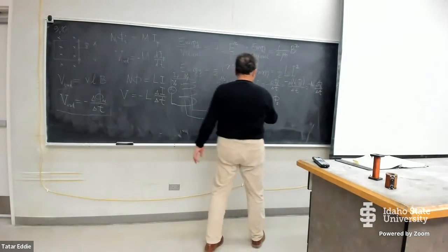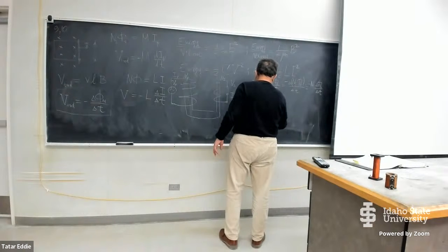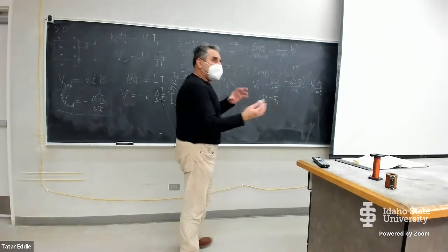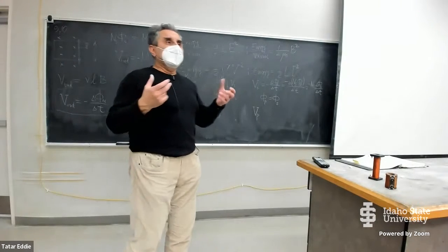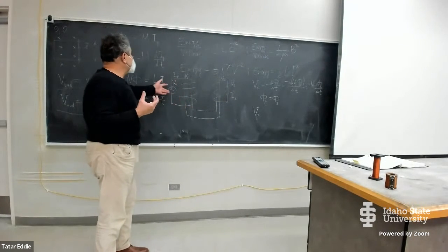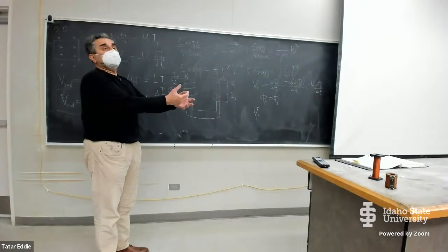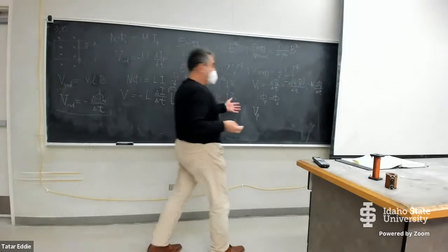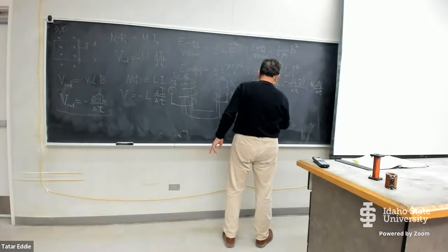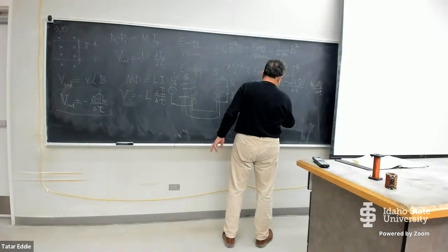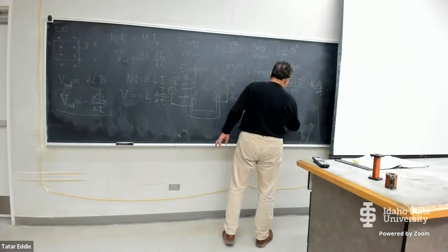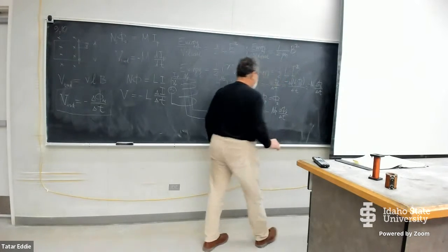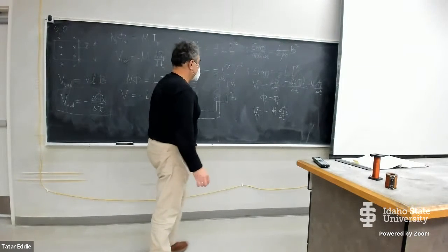Exactly the same formula you can write for the voltage in the primary. So in the primary, you have an equilibrium between the voltage that is provided by the source and the self-induced back voltage. But the result is going to be some voltage that is equal to the number of turns in the primary times the rate of change of magnetic flux in the primary divided by the time interval during which this change happens.